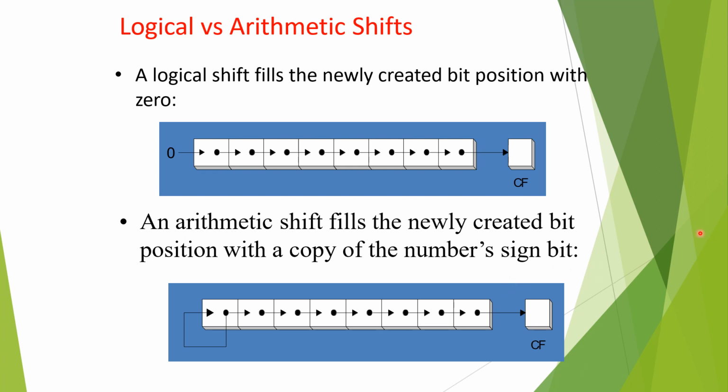First let us understand what logical and arithmetic shifts are. A logical shift will shift the bits to the left or right without preserving any of the bits. So the bit will be directly positioned to the next left or right according to the right or left shift. But in the case of arithmetic shifts, we have to have the sign bit preserved. That is, the MSB of the bits has to be preserved and it does not vanish once the shifting operation occurs. It has to stay in its position.